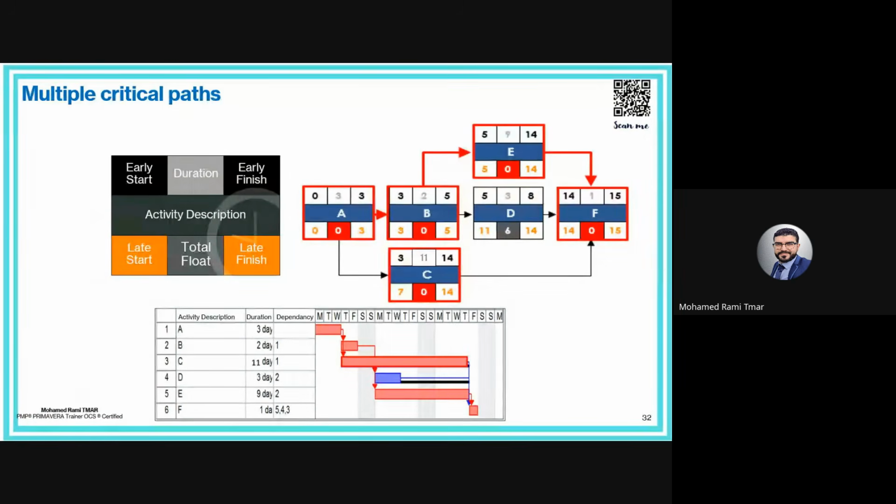More explanation to make it simple. Let's take a simple example. We have, for example, path A of 20 days, so it is the longest path. And path B is 18 days, so near critical with only 2 days of float.